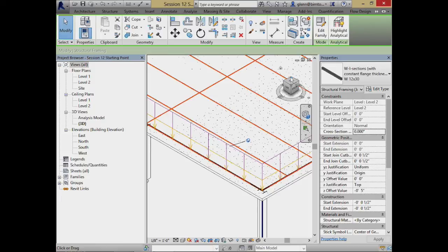If I go through and change something in Revit, we can take it back to Robot. If you change some more in Robot, you can take it back to Revit. And I'm using Robot as my example here because it's what I have loaded on my machine, but if you want to do that with ETABS, the same sort of functionality works there. So I did it to a steel frame structure. If you want to try it with a concrete frame structure, it should work essentially the same. It's the same basic algorithm, different types of code being used, but it should take you both ways.